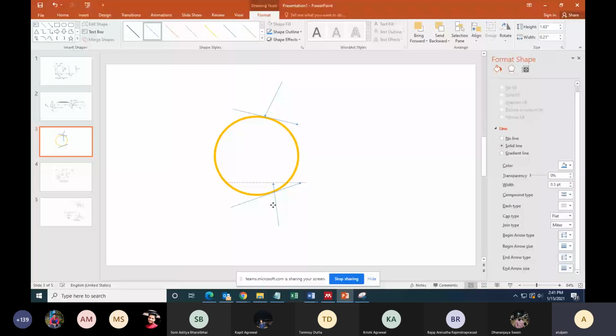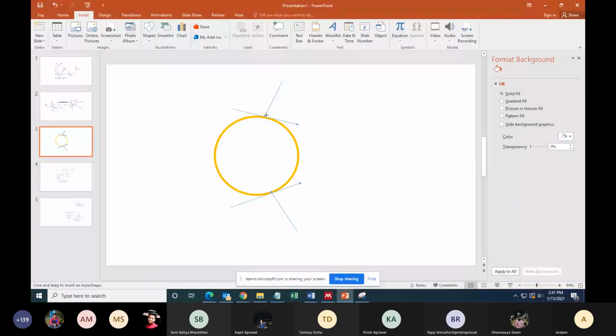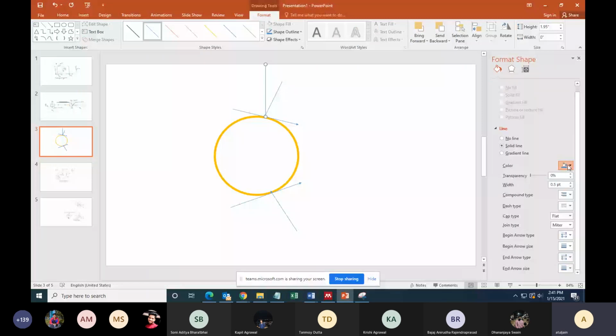Is this correct? Anything else? And this angle is 10 degrees. You can do summation Fx is 0, summation Fy is 0. You can solve and you can still get the value of N. Mu s, I mean.